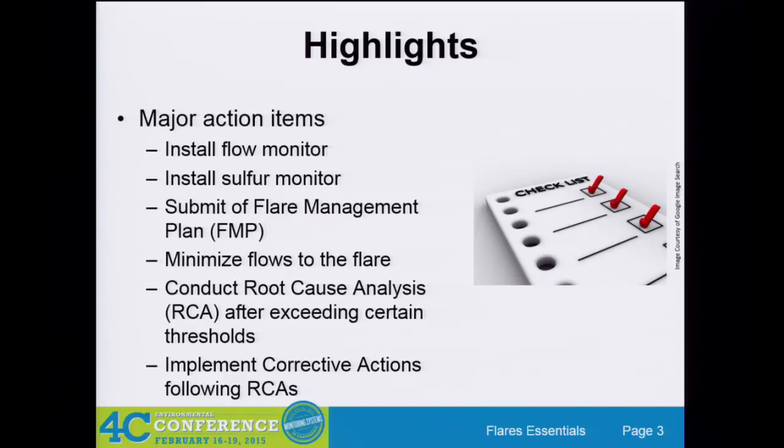Another part of the rule is you need to put together a flare management plan. This becomes a theme with all these regulations. You've got a regulation, you've got to have a plan. Because you've got to have a way to document what you're doing and how you're complying. The flare management plan basically has two sides to it. It has a side that says, what do you have? Tell me the specifics of your flare system. And then the bigger part is the minimization assessment. You are required to do a minimization assessment of your flare to see if it's possible to reduce the flow to your flare.